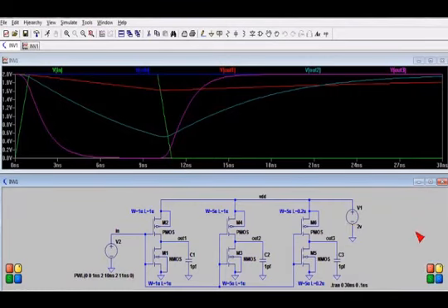So hopefully this gives you the idea that a very wide channel width gives a better drive. It produces more current to discharge and charge the capacitor, and a very narrow channel length provides more drive current and makes the inverter faster.